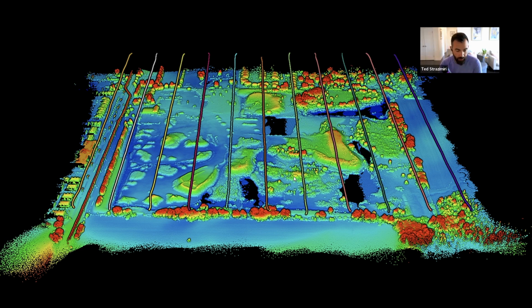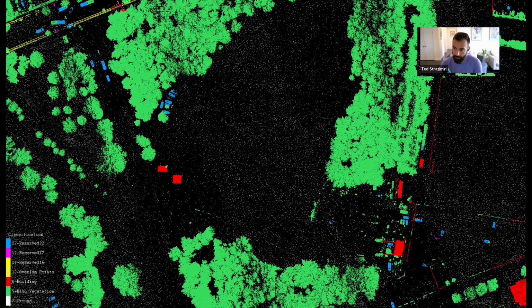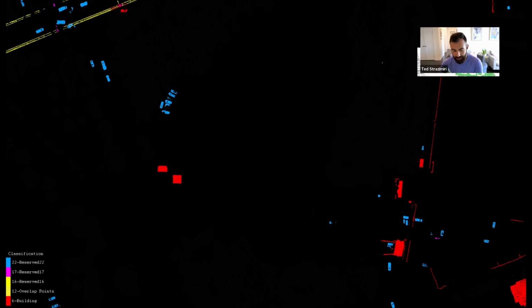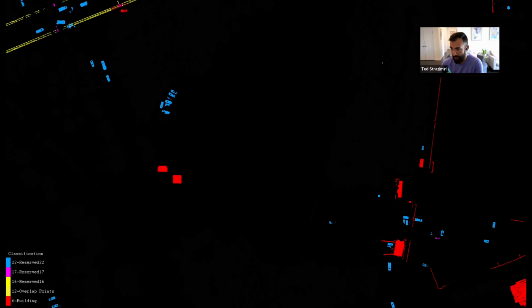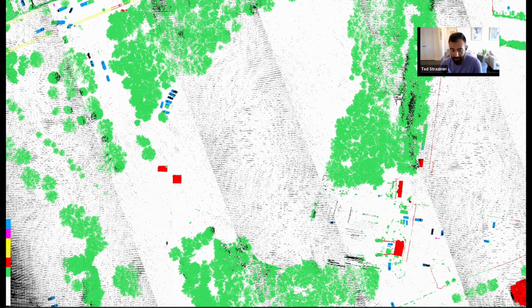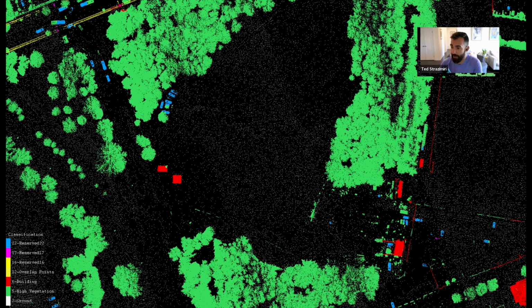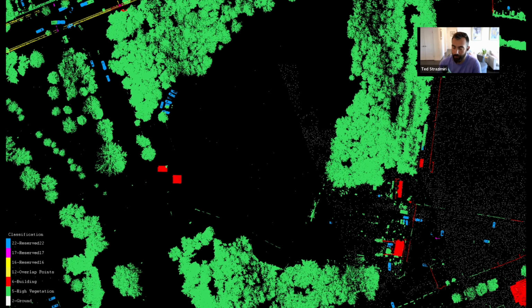So this classification, like I showed you here, it just depends. It's looking at the shape of the point cluster, right? It's just looking at the geometry that those points are creating. So if you have consistently realistic points that match what that object is and what the labeled information that created that model was, you're going to have much better results with this type of workflow and this automatic classification. So I think that would be really the winner in terms of the urban setting. But again, I think both are equally valid. It just depends on the job and the tool that you need for it.